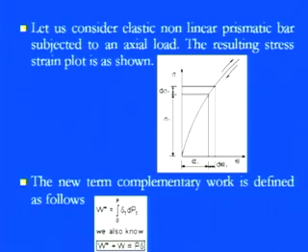So the new term which is coming as the complementary work is to be defined as the integral from 0 to P, because the load application is P, which we are limiting, of delta 1 into dP1, where delta is the deformation. Or we can say that the total work coming in that particular deformation is W star plus W is equal to P into delta. So the total work is the complementary plus the real work, and it is equal to the load application and the corresponding deflection.